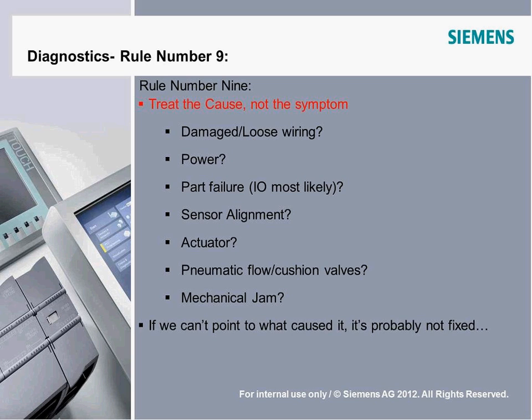A big one oftentimes is flow valves and cushion valves. We see this a lot on cylinders. Flows are what you see on the back side of the piston. They allow the air out of the extension side slowly, so it slows down the cylinder movement. Those things can go out of adjustment all the time. If it's all the way off or clogged, then it stops the whole thing.